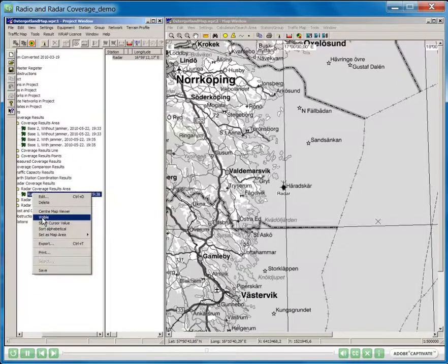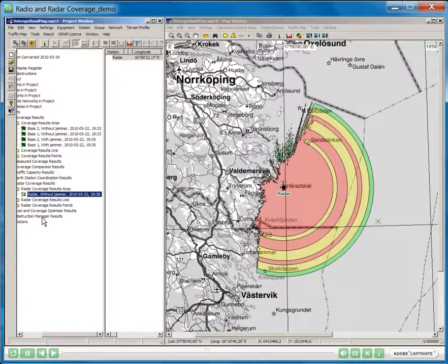Okay, and let's display the result. It looks like this. Red again was the 1 square meter, and yellow was 10 and 100 square meter. It's typical that the radio optical horizon is somewhere around here, so it's not feasible to get a very much larger range. Let's see what range we got. 36 kilometer or so.